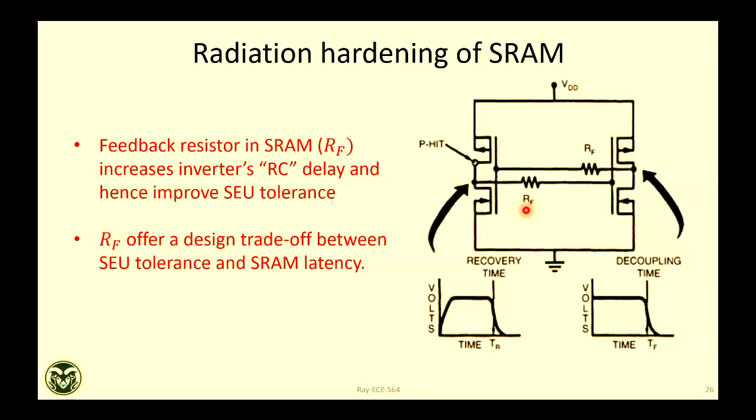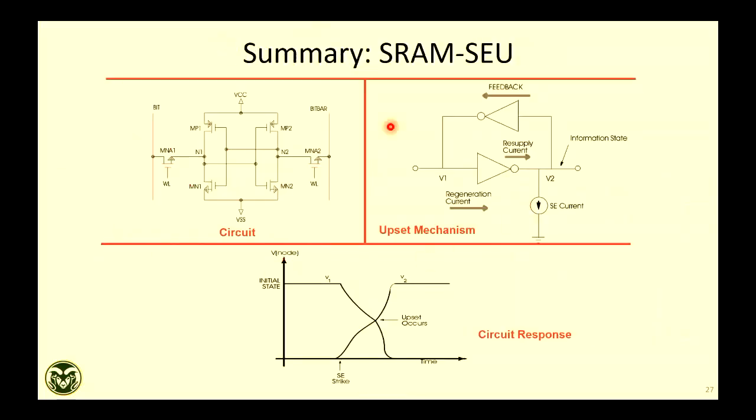Just one simple example. So this is what we learned so far in SRAM, that radiation dynamics is far more complex than in DRAM because there are multiple junctions sitting around. So you need to look at which junctions are more critical connected to this storage node, right? And the timing aspect of the inverter, or inverter delay, plays a big role in critical charge determination.